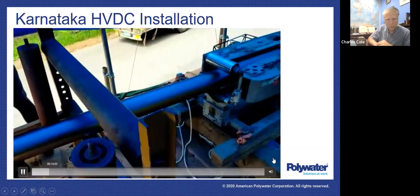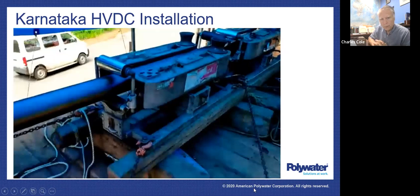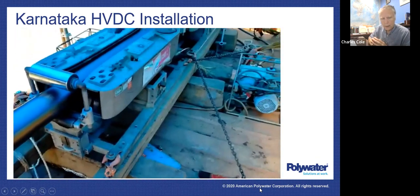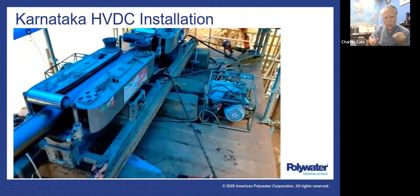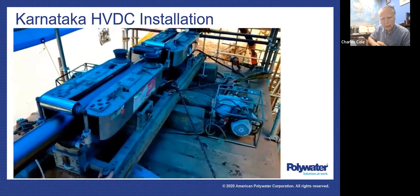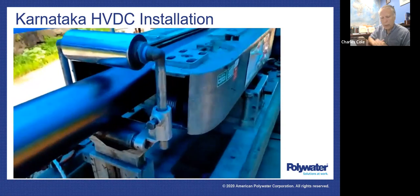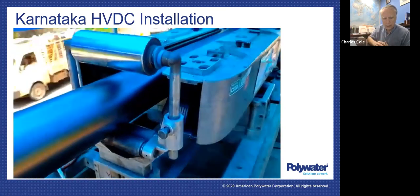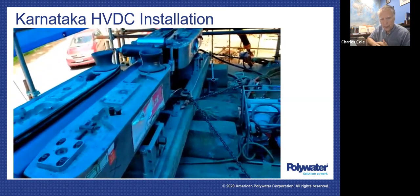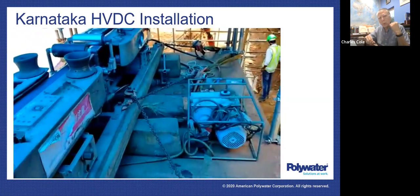So here it's coming off of the reel. It's going through a pusher. A pusher reduces the back tension on the cable, and it also helps to pull the cable off of the cable reel. Back tension is important because it's basically creating more tension at the start of the cable installation inside the duct. So if you can reduce that back tension, because there's a tendency for cable to want